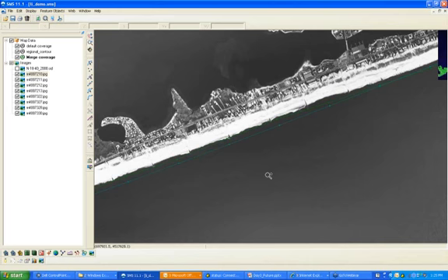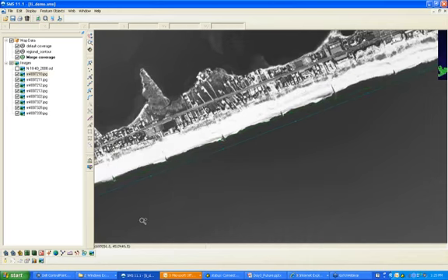And I'll draw about 3 or 4 so you can get the idea of what you'll need to do. So again, we're going to go to Create Feature Arc, and we're just going to draw lines. So we'll start here, and then we'll make our ending position. And I'll draw the same thing for each one of these groins along the shore.